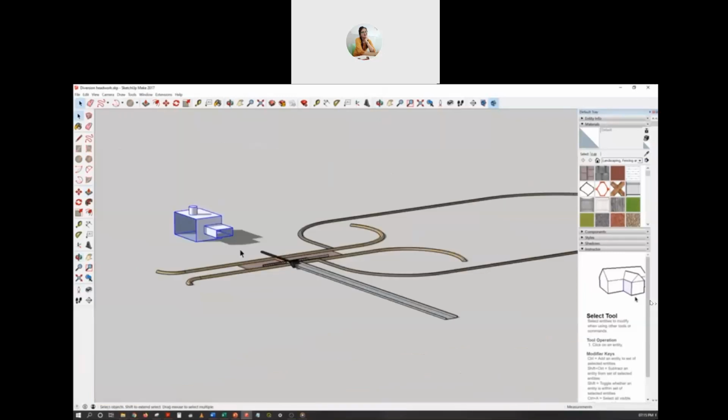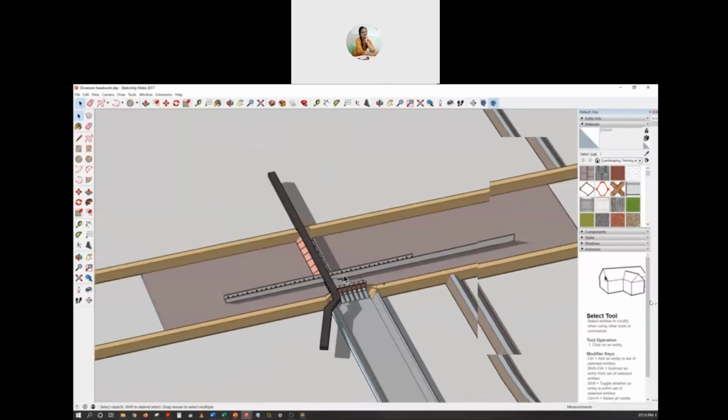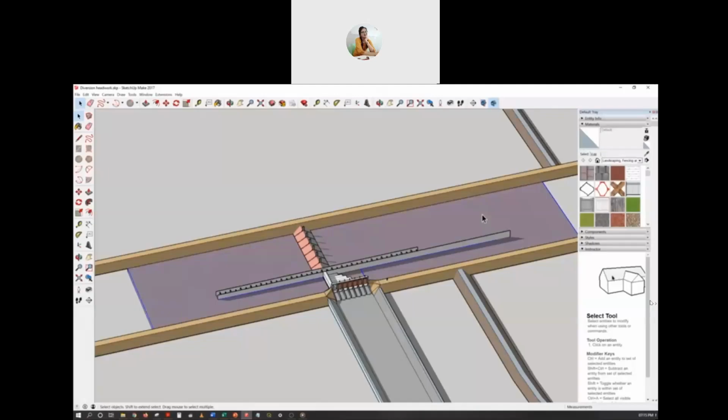One more thing, you see, I've made from here to here a floor. So this is called the weir floor. Now, that means this portion and this portion is not just a river bed. There is a concrete or masonry impervious floor, which is provided from here up to here.